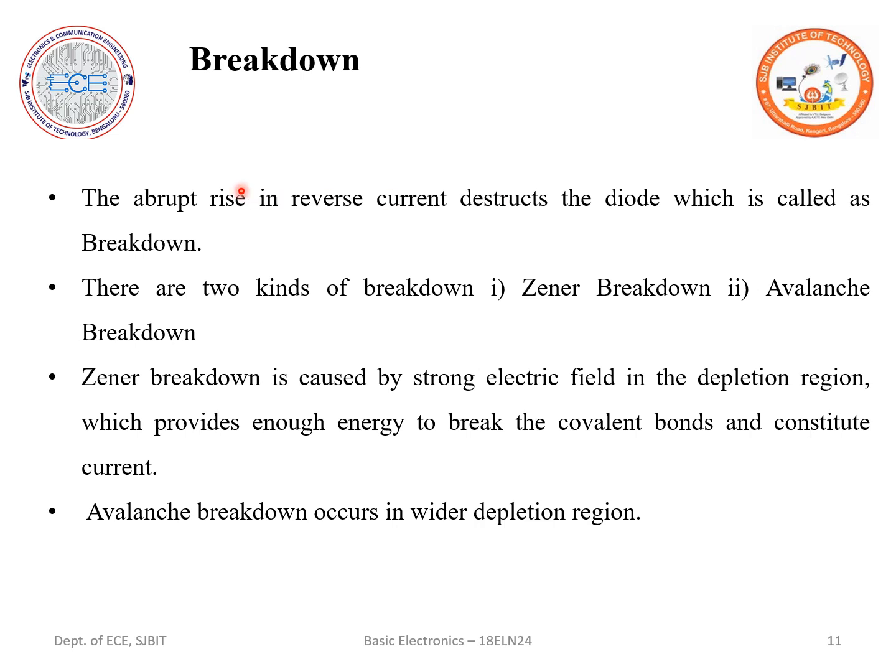We already studied what a breakdown and a breakdown voltage are. As and when we increase the reverse voltage, more and more holes and electrons get neutralized. The majority charge carriers get neutralized, and it is only left with the minority charge carriers, which constitute a reverse saturation current, and that voltage we call the breakdown voltage.